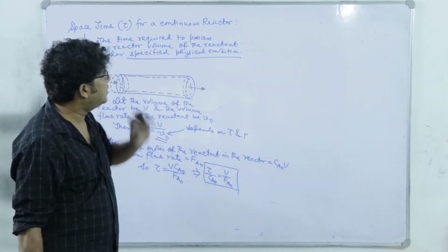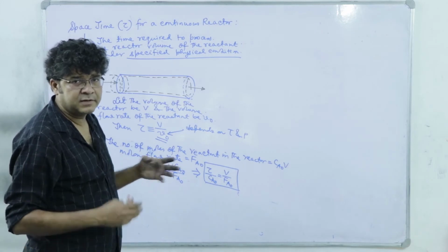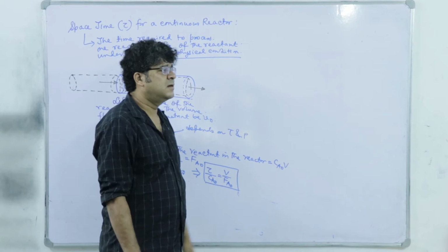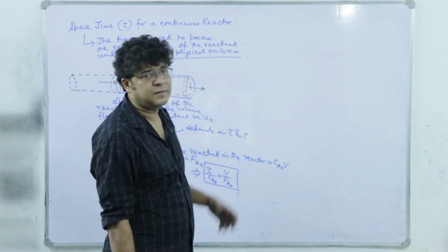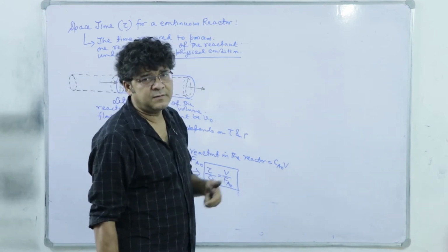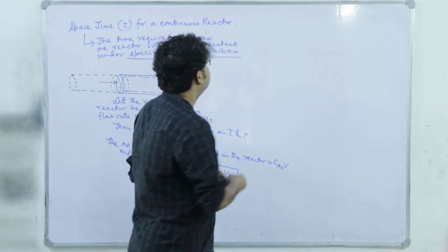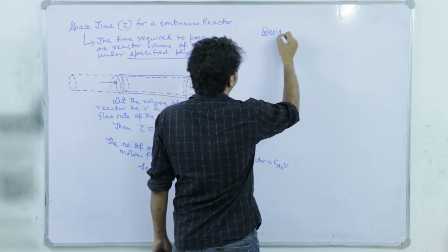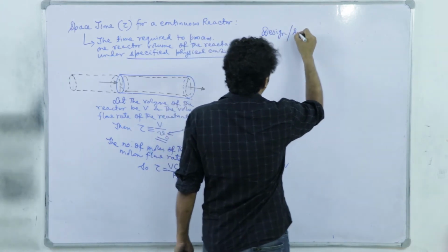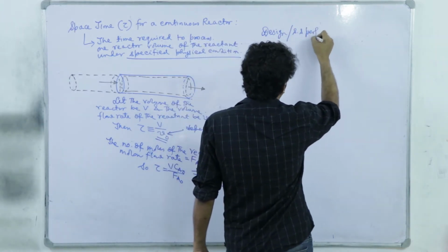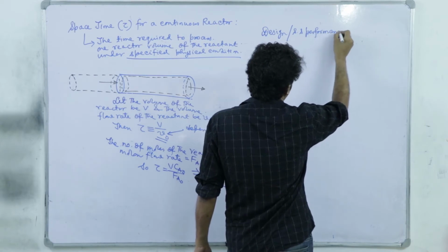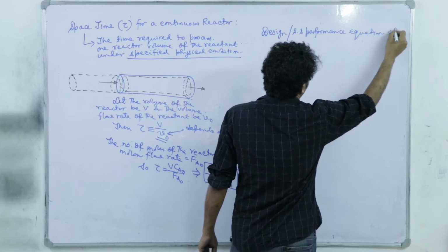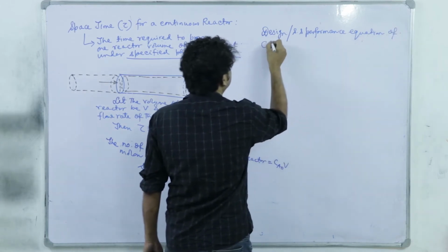Now, with that understanding of the space time, let's go for solving the design equation, right? That is a steady state material balance equation for CSTR and for PFR independently. So, design or steady state performance equation of CSTR.